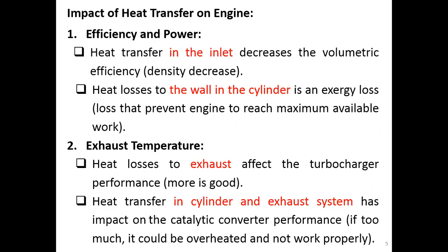If we do have heat transfer in the intake manifold, where our mixture flows before it gets into the cylinder, it will decrease the volumetric efficiency. Because what happens? Heat flows into the intake manifold.